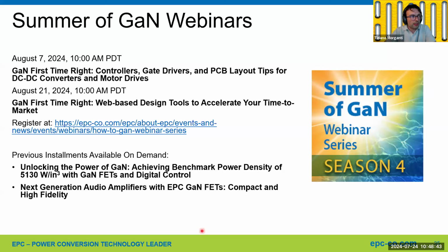I have not tried them for one reason. They start to have forward voltage, which is around 1.5 to 2 volts, which is already removing the advantage you can get with them, because our GaN FETs have a freewheeling voltage of about 2 to 3 volts.